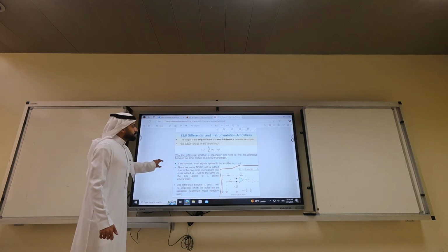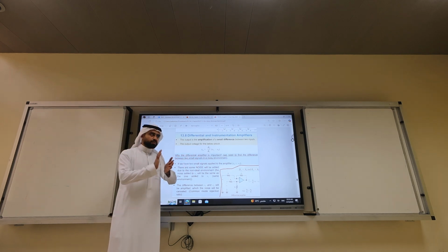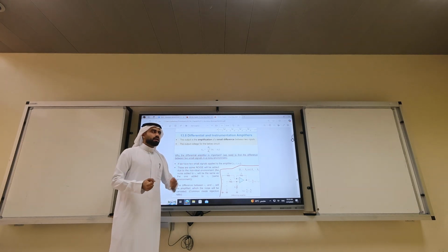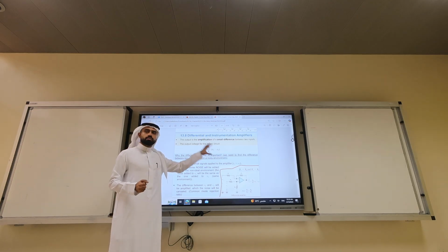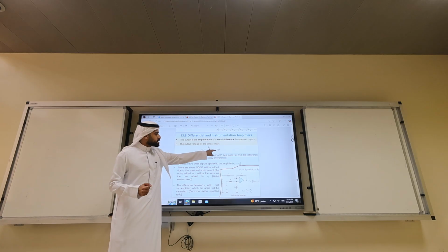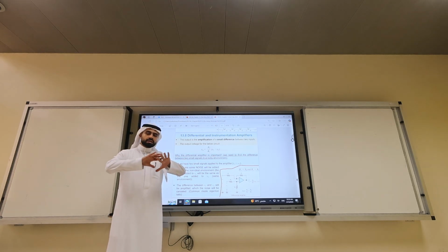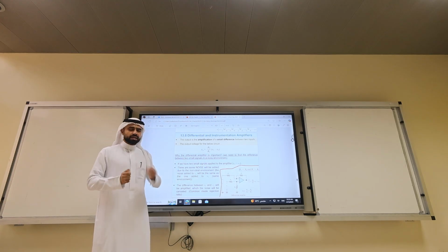So here, for example, the actual voltage that appears from the pressure of signal 1 and signal 2, you subtract them, then you can get some sort of an indication of your measurement. It converts the difference between input 1 and input 2, eliminates whatever noise and unnecessary information, and you subtract the difference.